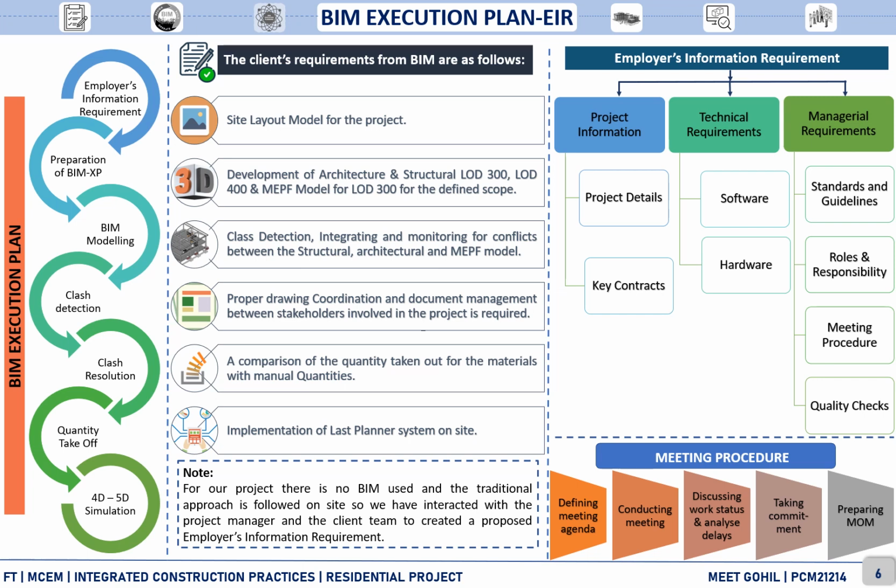Clash detection, integrating and monitoring of conflicts between structural, architectural and services models. Proper drawing coordination and document management between stakeholders involved in the project. A comparison of the quantity takeoff from the software with the manual quantities applied on the site. And at last, implementation of the last planner system on the site.